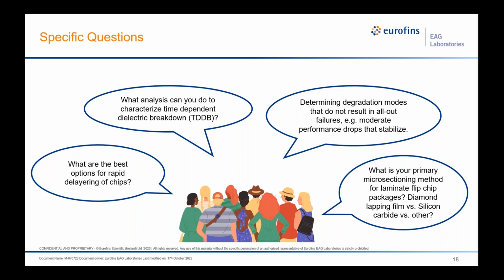Some of the techniques that we use for delayering may be mechanical, parallel lapping or just polishing and removing the layers physically. And then there's a chemical approach, etching copper or aluminum, where the endpoint would be the dielectric in between. And then plasma reactive ion etching we could utilize as well to remove certain ILDs and dielectric materials. So in a process, we may use a combination or all three to remove each layer selectively for an inspection.